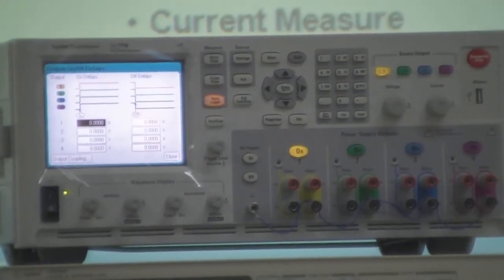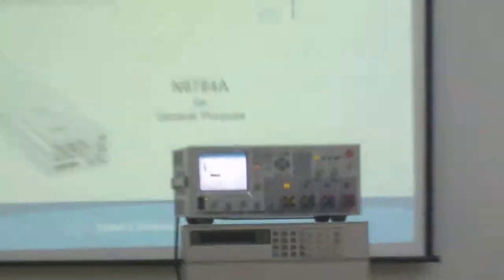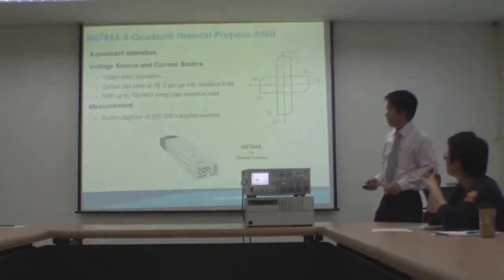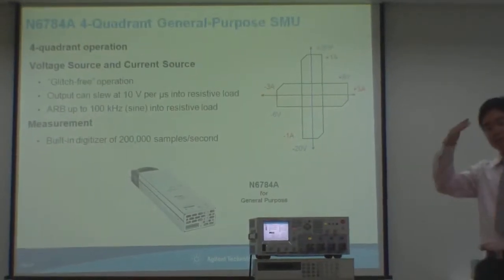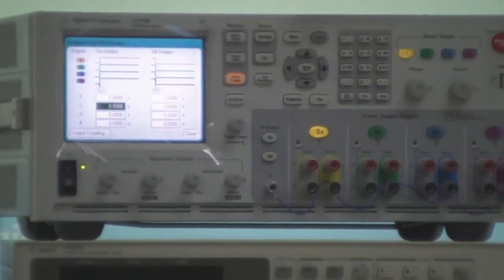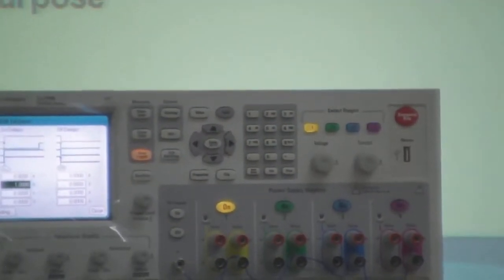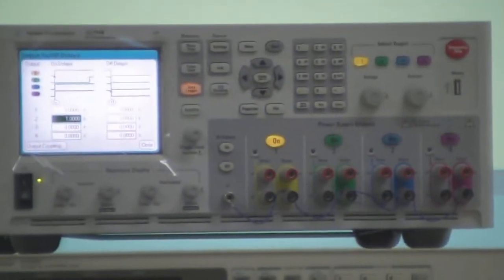As we saw in the previous slide, you can have different ramp-up times for different channels. If you want channel 2 to come on 1 second after channel 1, we just put a 1 second delay here. What you program in is exactly what you're going to see. It shows you graphically right here how it turns on, so you can see exactly how it turns on and whether that's the way you want it to turn on.